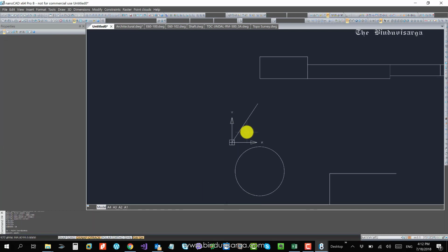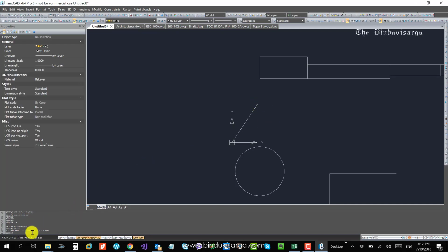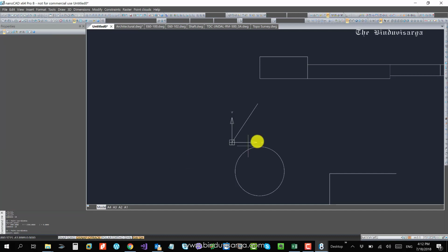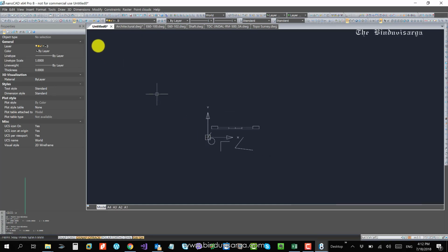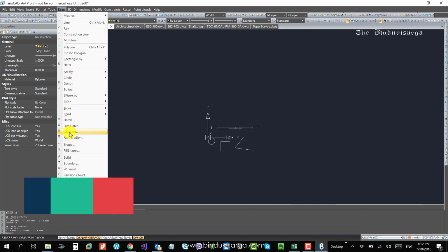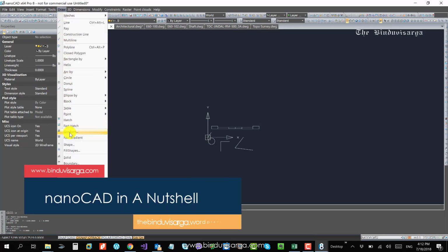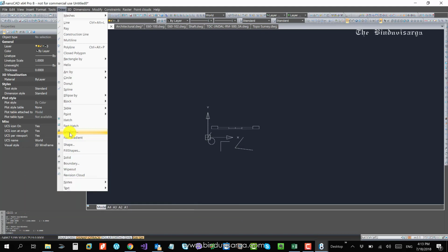If I use ID, enter, to identify the coordinate, I can see, yes, it's X and Y. The value is showing. Y is 1500, and with ID, the coordinate should be 0,0. Yeah, that's correct, 0,0. So it works the same. This is true for all the geometrical primitive creation tools. So you can try it yourself. I'm sure you're going to have fun with all of this.